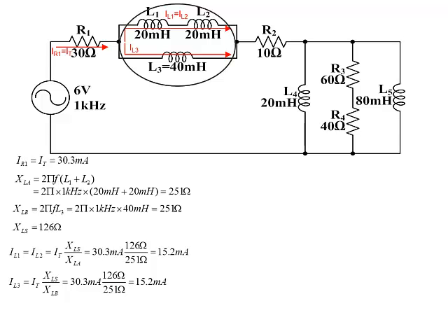The current through each branch should add up to the total current flowing into the junction. The current through the two branches add up to 30.4 milliamps, which is slightly higher than the 30.3 milliamps of current flowing into the junction. This difference is due to rounding off errors. The current through each path joins together again to become I total, which flows through resistor R2. This means that IR2 equals 30.3 milliamps.